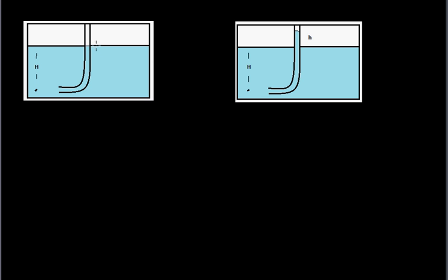When it's stationary, there is no height of the fluid, and when the boat starts moving, you can see that the fluid rises in the Pitot tube, and that height will allow you to determine the velocity. So you can just draw streamlines. Imagine this is in motion. Okay, so let's go ahead and do a Pitot tube problem, at least symbolically.